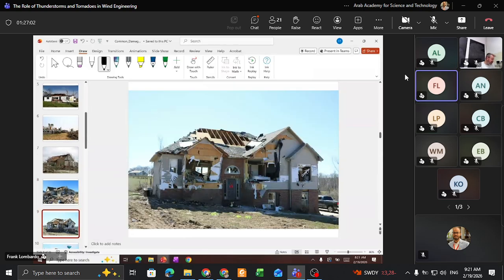Okay, another example. This one is definitely Tennessee in the U.S. So this is basically in the southern U.S. Okay, you can see a lot of different things going on here, talking about progressive damage. Windows and doors missing. Okay, so you have this sort of cladding damage. You can see this vinyl siding here that's been ripped off. Okay, you start to see these pressed wood planks. That's the roof deck here. Here's the actual roof structure. Okay, these are trusses. So you can see a lot of damage here to this particular structure.